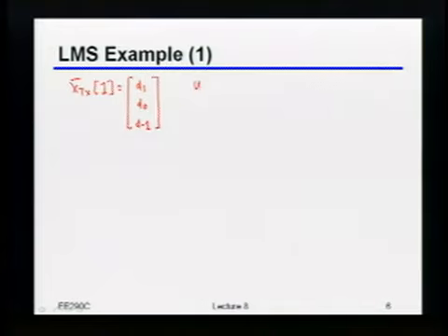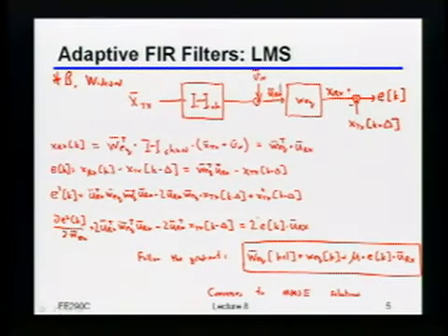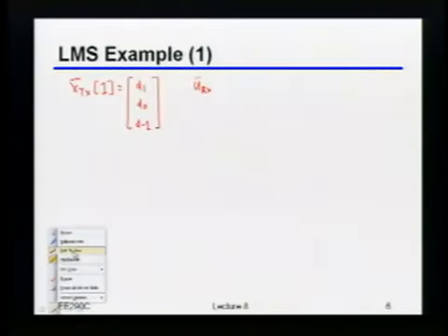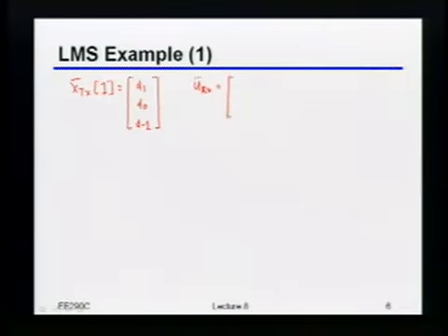Okay, so now if I look at my received signal, and remember this u_rx is just what's actually going into the equalizer, that by definition is going to be u of 1, which is the analog input in the equalizer at time 1, meaning associated with data 1, plus some noise at that time. Okay? That's u_rx of 1. One bit time ago, it would have been u of 0 plus v_n of 0.